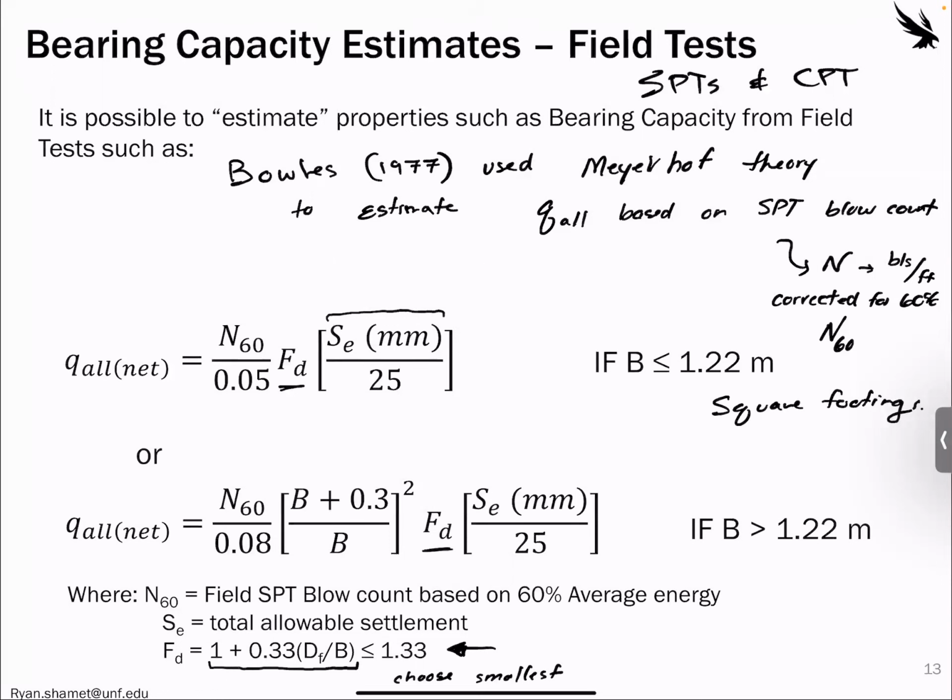I know when I was working at Terracon, Dennis, I don't know if you had to do this at all. They have a whole chart system where you would find the SPT corrected blow count, and then this essential curve, like a curve fitting, where you would plot it on the x-axis, read where it intersects, and then find the corresponding Q net allowable for the y-axis. So something like that.